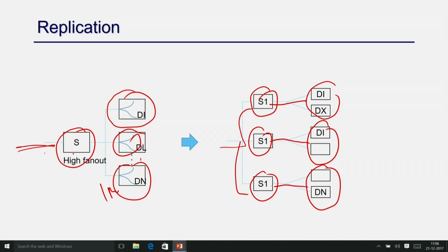So, maybe I just created 3, and this 10,000 can be split into, say, 3000 each. You can copy it to 10 copies, I just keep 3, but you can actually create 10 copies, and all of them have less fan out now. And whenever the number of fan outs is less, the possibility of placing those fan out nodes nearby is high.